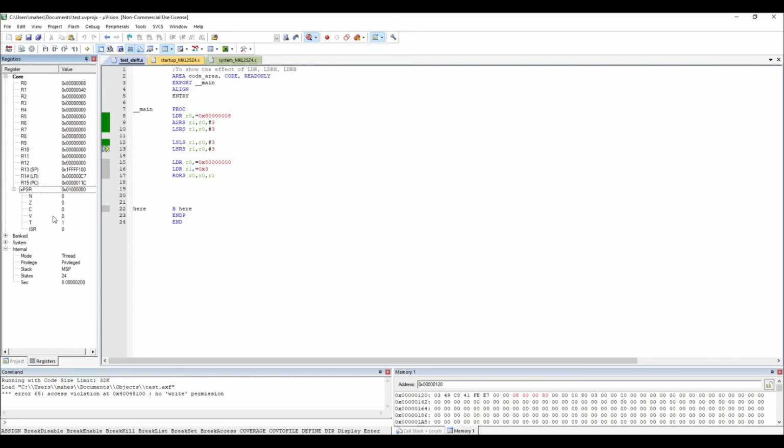Not really, because the carry flag is also 0. It is 1 0 0, which is getting shifted out, and the last 0 will go to the carry, so the carry is also 0. It doesn't matter, right? You can just play with it. I have a suggestion here: change this to something like 9. Or rather not 9, because it should be 1 0 1, then only the carry flag will be set. So 1 0 1 0, something like that.